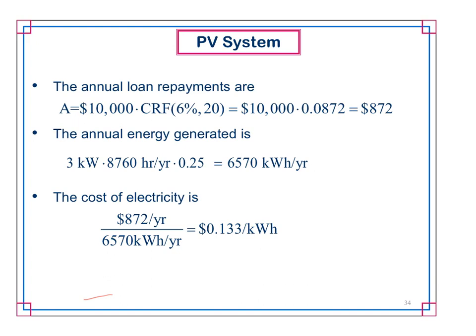Don't you actually need a special setup to be able to use your own system when the grid is out? Well, the question is, do you need your own special setup? You have a PV array that takes DC, and there's an inverter that converts it to AC. Your house runs on AC. So as long as the sun's bright and shining, and you are less than 3 kilowatts of energy consumption, will the lights stay on once the grid goes away?